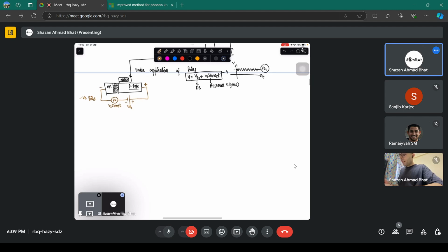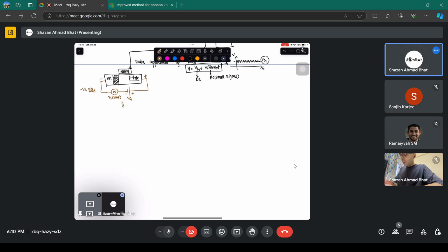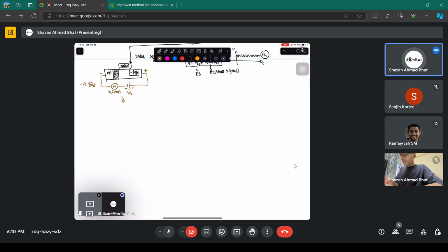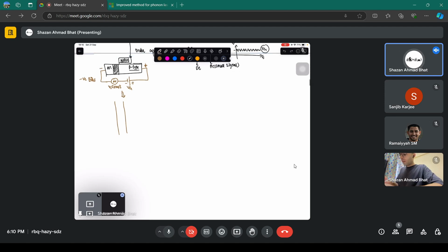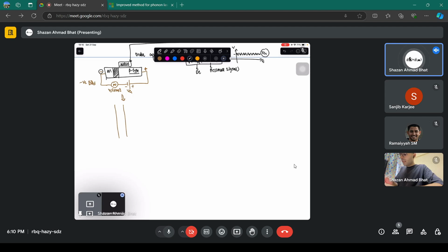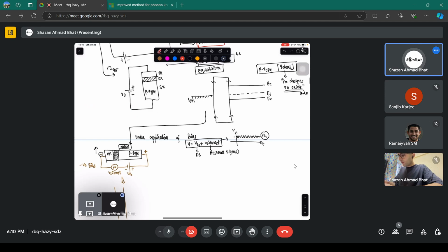Small signal. Now, what happens because of it is that when you draw the band diagram, you know that this is the oxide in between. Let's first show the oxide like this. Let's not worry about the conduction band and valence band of the oxide yet. What happens is that because of this negative charge, the Fermi level on the metal side rises, because negative increases the electrostatic potential energy of electrons. So the Fermi level of the metal, EFM, goes up as compared to that of this scenario. This rises because of the negative voltage.